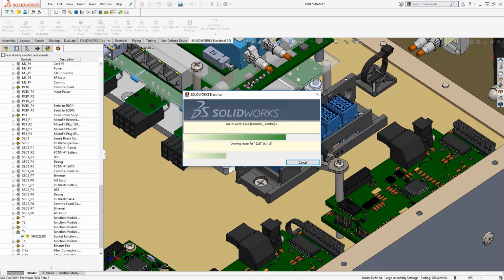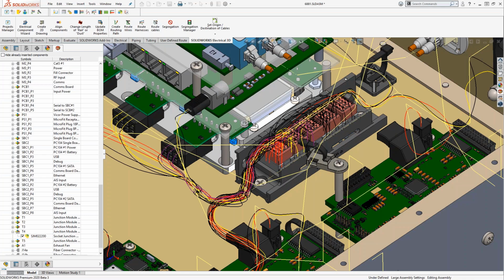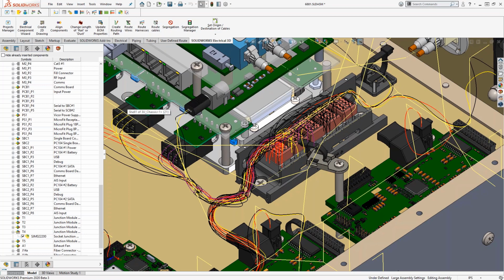So if you see there on each one of those, it's A, B, C, D, E. So every single one has a connection point correlated back to the electrical side. Well, once it figures out the wire styles that they're going to route, the properties, remember the 20 gauge wires, we showed one of them before, but each one of those wire styles has a property to it. In this case here, I routed these as sketch lines because if we were to route them in full solid route, it would take quite a bit of time to route.